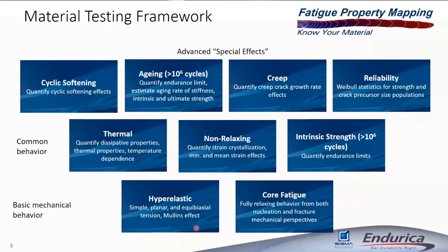You need to know your hyperelastic stress strain law, as the earlier talks were addressing. You also need to measure what we call the core fatigue parameters. So we use a fatigue crack growth rate curve, and we use a measurement of the size of crack precursors in the rubber. That's the bare minimum information you would need to do a fatigue calculation.